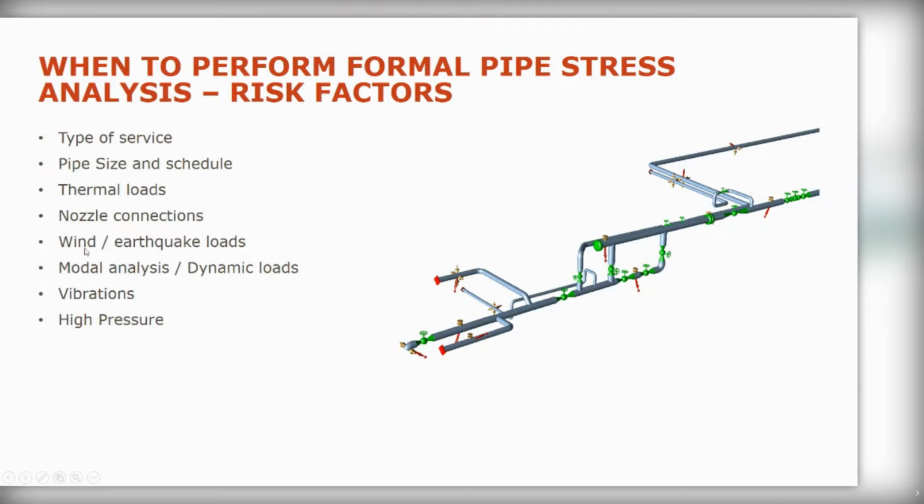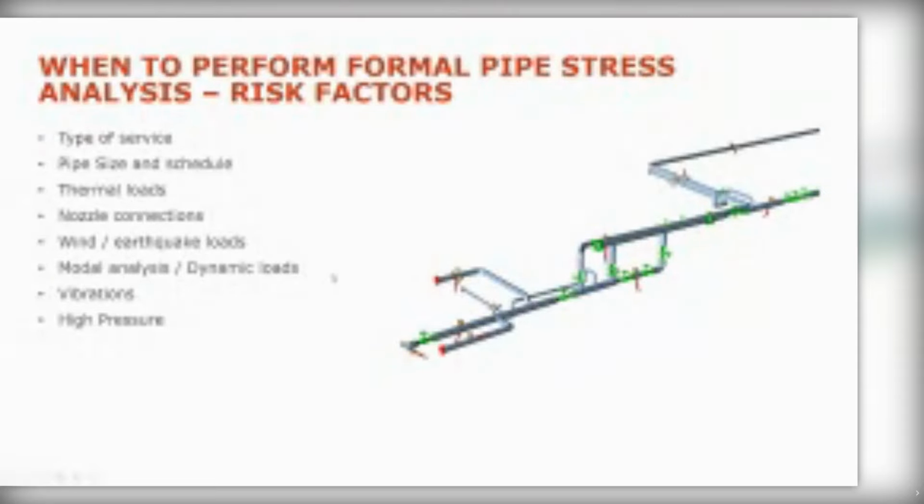Wind, earthquake load. Those can be done by hand sometimes, but often enough it's easier to do using software. If you require modal analysis, so you want to check the vibrations and the natural frequencies, again, it's something that is a lot easier to do using formal pipe stress analysis. So that will drive you towards it if you have vibrations.